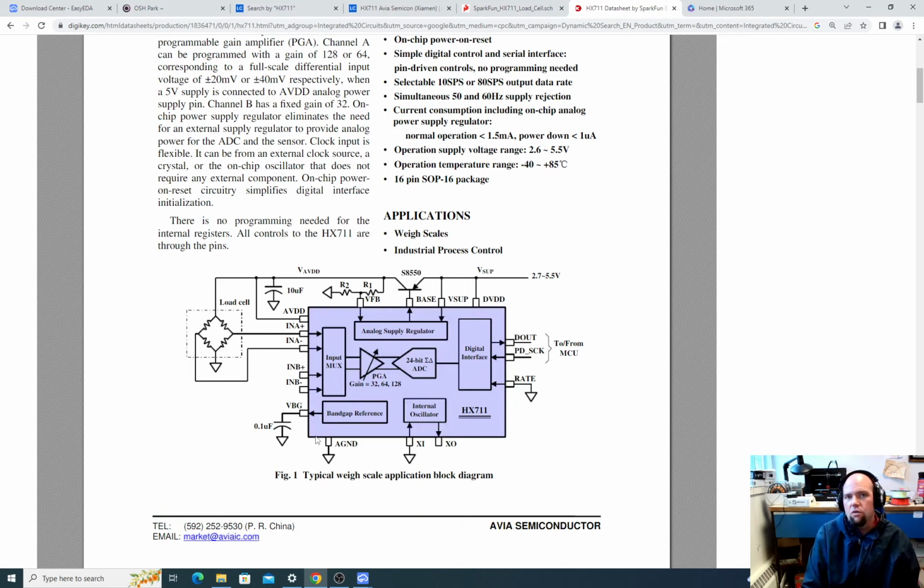For silicon, that's normally going to be about 0.7 volts. Sometimes these band gap references are closer to 1.1 volts. It depends on the actual process technology they're using. But it's normally a very precise known voltage value. So it's an easy way to make a voltage. Effectively, this band gap reference is saying if you have a diode and you run current forward through a diode, you're going to get that diode voltage across it. That's what it's using to generate this voltage.